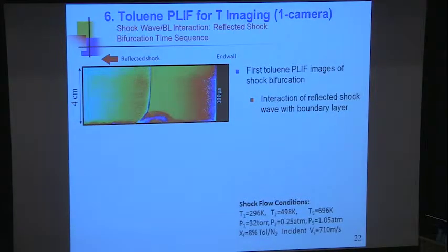And now this is what we were after. When the shock wave gets to the end wall right here, it goes back. When it goes back, there's this sidewall velocity boundary layer that this wave has to interact with. And this is called the reflected shock bifurcation zone. And so we like to forget it. We like to pretend it's not there.